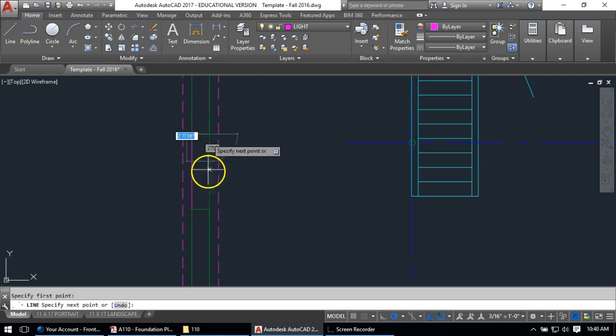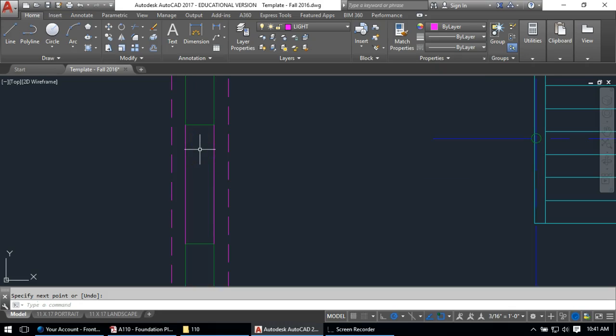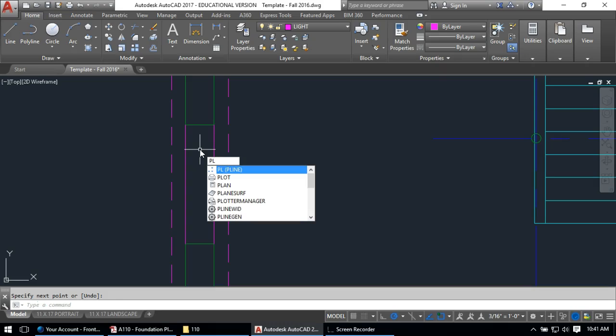And I have to draw on the sills. So again, good practice is that the wall layer comes around like this, and then the sill gets the layer there. And it's hard to see the exact detail of these windows. They've got a nice little detail here. I might even simplify it further. Again, that tag's going to tell us information, but I don't even have the whole set yet, so I'm not sure what information is provided for this window. So I might have to make some assumptions at this point in time.